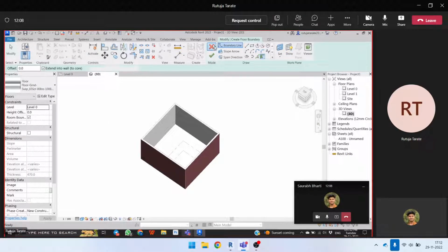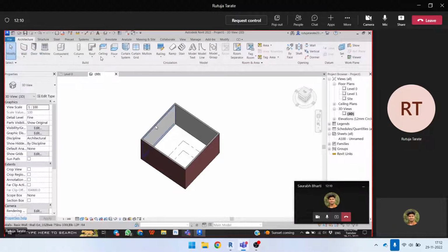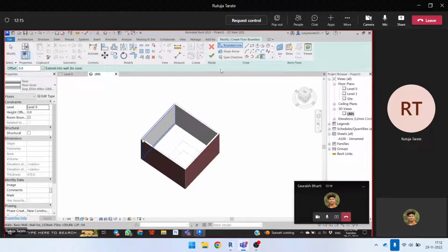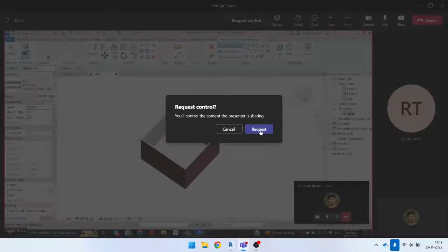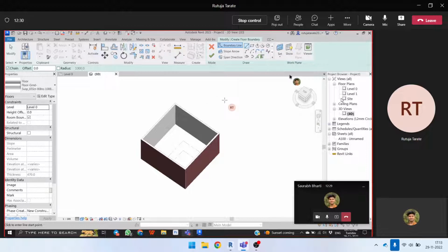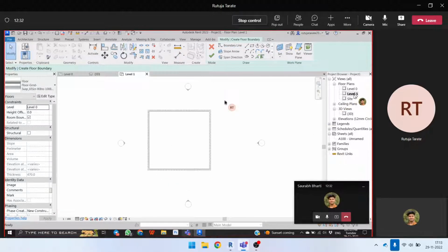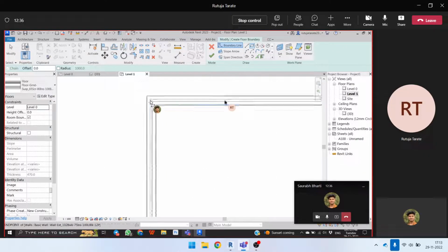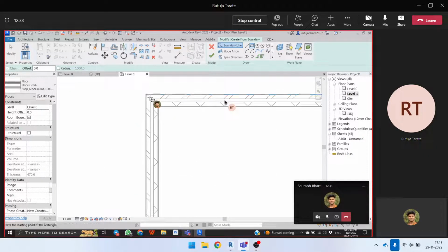Finish it. And the floor is here, as you can see. This is floor architecture. In 2D or in 3D, if you want to draw it in 3D view, that's all right. You can use the pick lines or the rectangle, whichever option you want. Now you can go to 2D view, use this rectangle button, and then choose from where you want to make the floor.